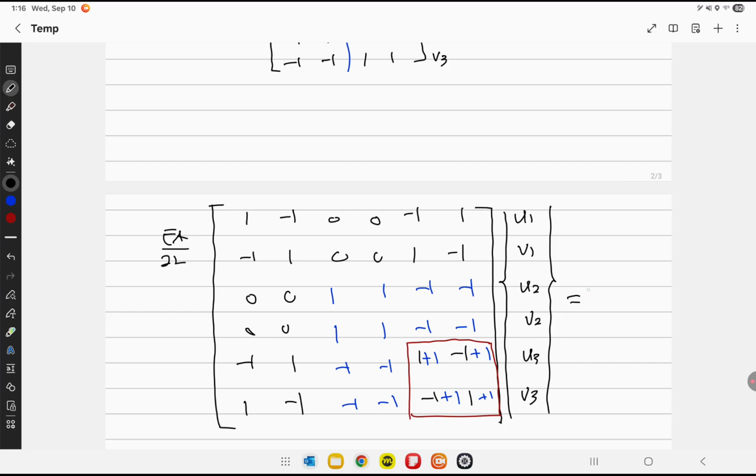To be complete, on the right-hand side, you have node 1 fixed, so you have R1X, X directional reaction, R1Y, Y directional reaction, R3X, R3Y. These are reactions whenever you fix the displacement. All right, what are F3X and F3Y in this problem? F3X equals F. F3Y, 0. So F and 0.